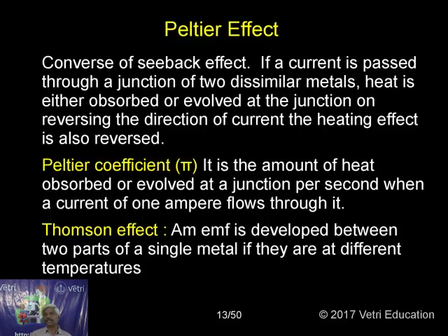Even though we introduce a third metal, it doesn't affect. If we introduce a third temperature, that affects the EMF. If we introduce a third metal, that also affects the EMF. But if we use lead as a third metal, it won't affect the thermo EMF. That is the purpose of using lead.